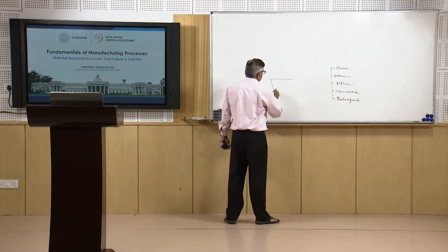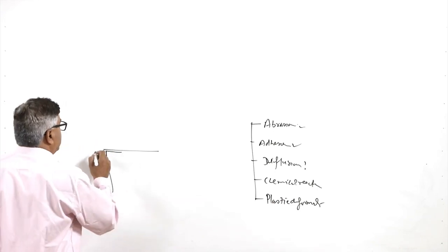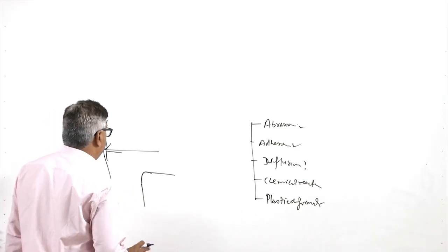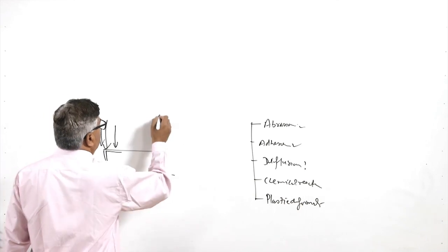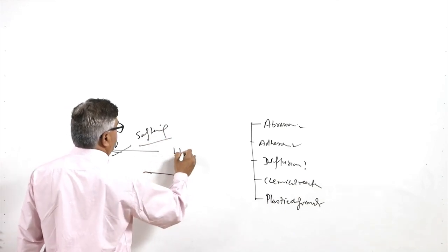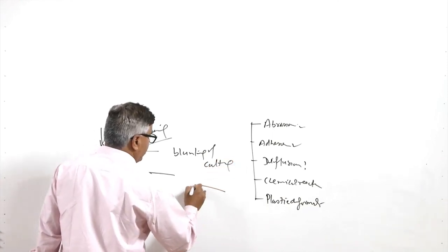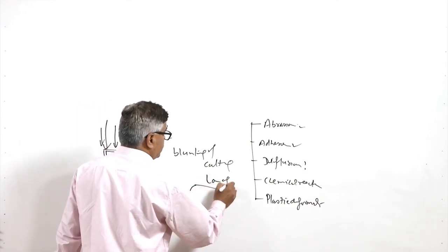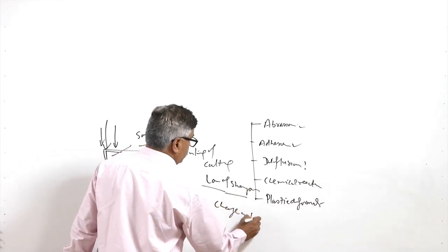Deformation is the case when the rise in temperature near the cutting edge is too high, then under the cutting forces, the cutting edge tends to get blunt or deformed. So, under the cutting forces acting during machining, the rise in temperature will cause softening of the cutting edge. Softening will lead to blunting of the cutting edge, and blunting will lead to an increase in the radius of the cutting edge, which means loss of sharpness as well as a change in the tool geometry.